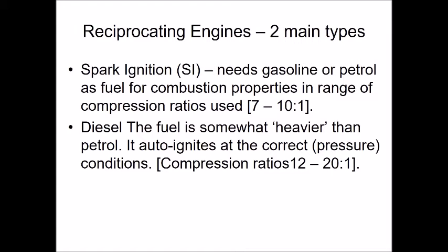So we put diesel fuel in diesel engines, and diesel fuel has a slightly wider molecular mass distribution, but it's also heavier. Heavier meaning its average molecular mass is larger than gasoline. It's got quite different properties. It actually needs higher compression ratios to burn. That's one thing, and the other thing is that it's not as volatile as gasoline. So because you can squash it harder, you don't need to hit it with a huge spark.